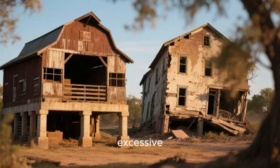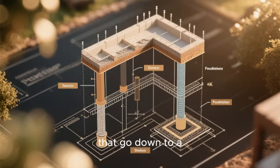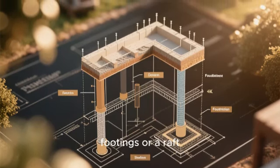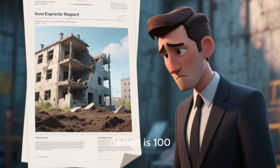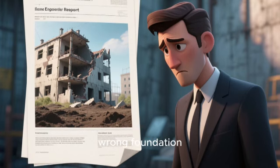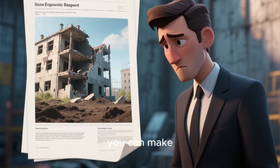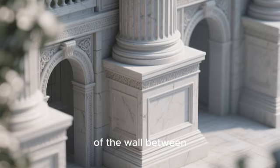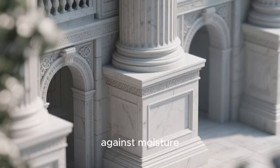This prevents excessive settlement. The foundation itself can be a deep system using piles or caissons that go down to a stable soil layer, or a shallow system like spread footings or a raft mat. A pro tip from geotechnical engineers is that the foundation design is 100% dependent on the soil report. Building on the wrong foundation for the soil type is one of the most costly and dangerous mistakes you can make. The substructure also includes the plinth, the portion of the wall between the ground level and the finished floor level, which acts as a barrier against moisture and pests.